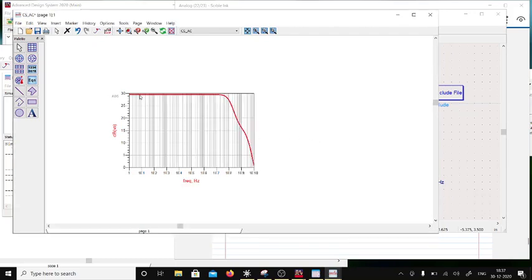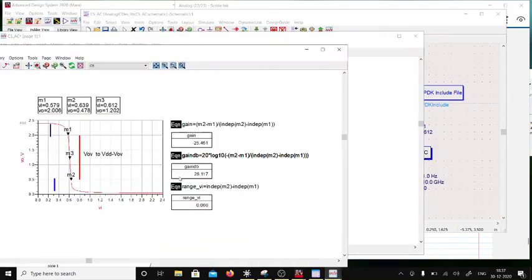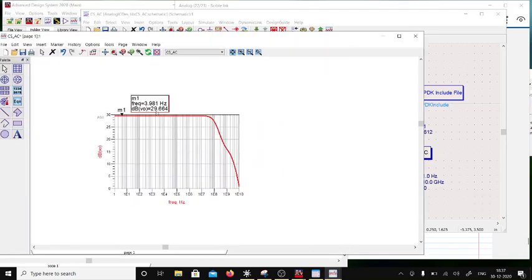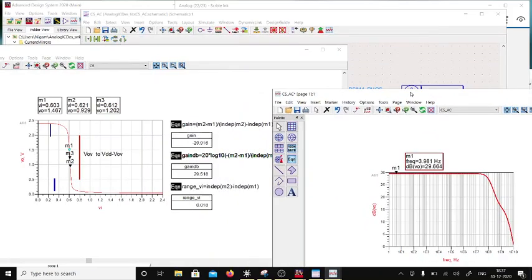So this is near 30. We figured out from our equation it was 25.26 dB gain. It turns out to be 29. That's okay, because what happened was in our curve, if I bring it to a very small region around here, the gain is 29 here. From the static response you also get the same gain, 29.5, and from the AC response 29.5 roughly. So it's just a matter of where you are checking it, right?